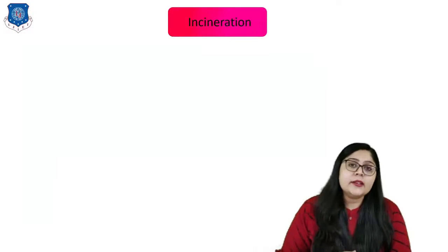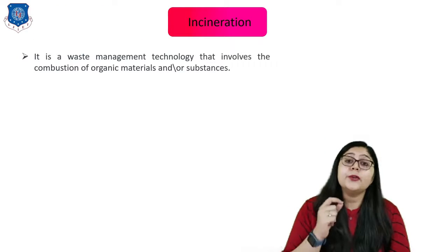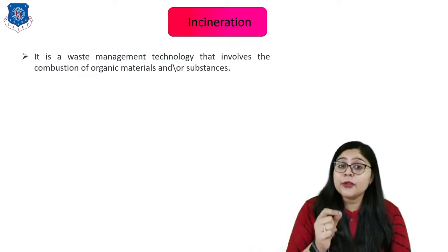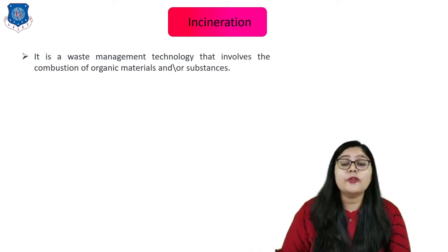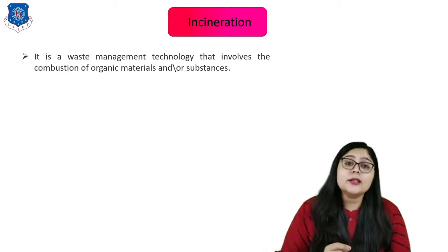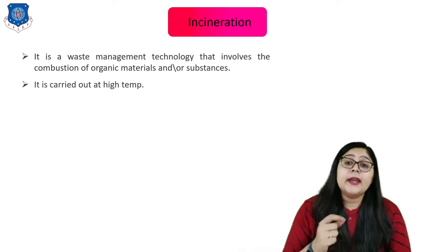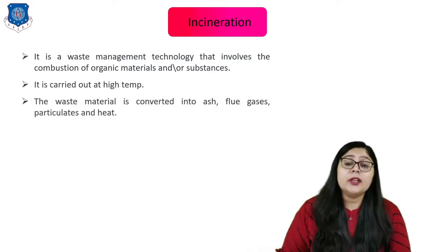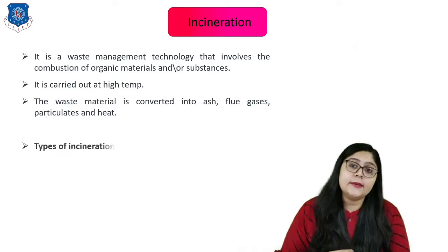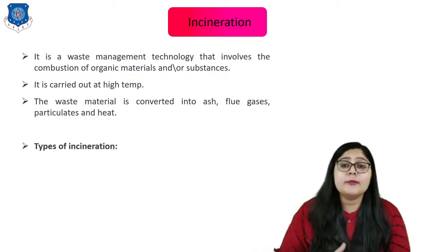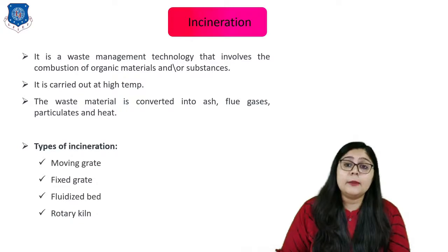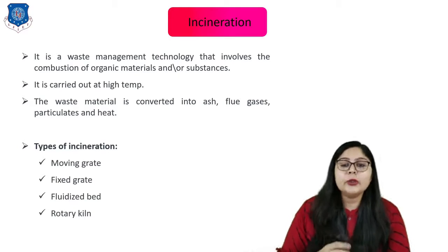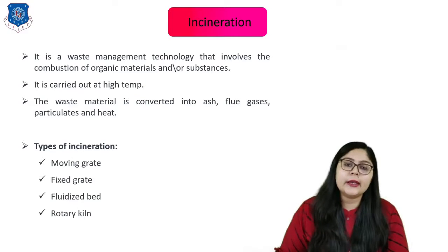Now what is incineration? It is a waste management technology that involves the combustion of organic materials or substances, carried out at high temperature. The waste materials are converted into ash, flue gases, particulates and heat. There are various types of incinerators, like moving grate, fixed grate, fluidized bed and rotary kiln.